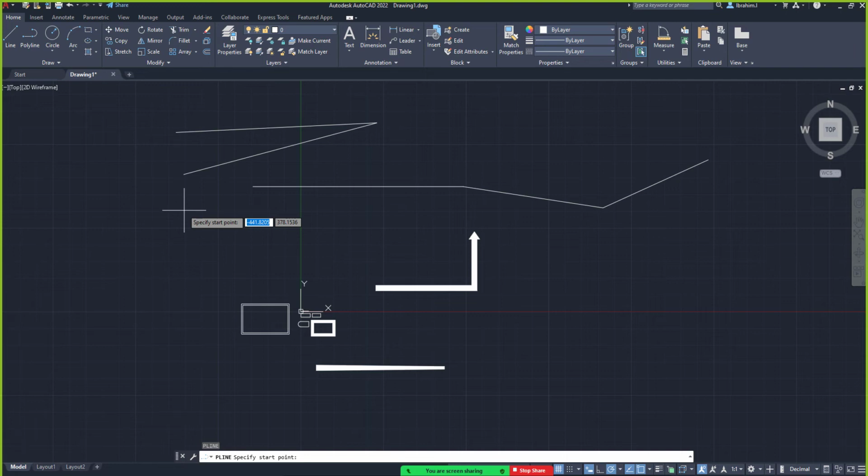Am I confusing you, or we are making progress? Escape key, enter key, and spacebar, 3 of them can end your command, but 2 of them can restart your command again, which is what? The enter key and spacebar. Yes. So those 2 can restart your command again. They can reactivate whatever command you have active before. They will reactivate it for you again, and then you can start using them again, right?